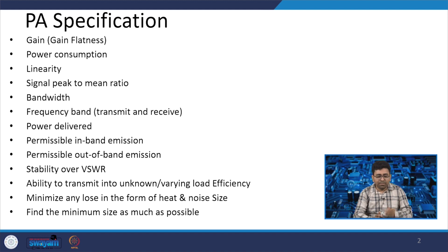Then an important parameter is the bandwidth. You should have sufficient bandwidth in your power amplifier, because we are transmitting a high bandwidth signal through the antenna, and the power amplifier also should ensure the sufficient bandwidth.